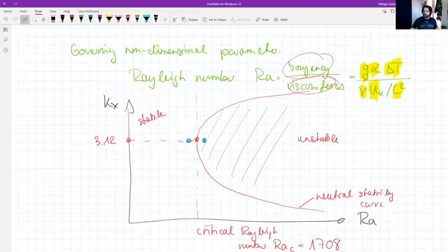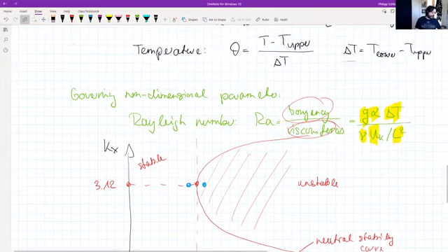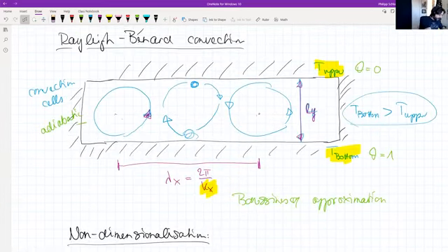Okay. So this is what I wanted to say about the physical aspects of the project. So it's these two cases, the lid-driven cavity and the Rayleigh-Benard convection case. Both have their own benefits, and both of them are used quite frequently in testing simple numerical methods. So they're not any strange cases. They both have their difficulties or issues. So for instance, for the Rayleigh-Benard case, as we'll also see in the results, we have this issue of the side walls, which just need to be far away.